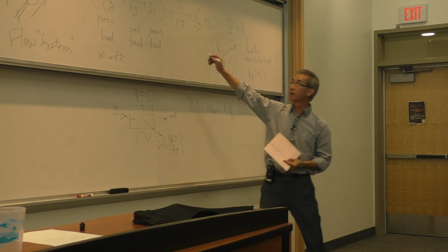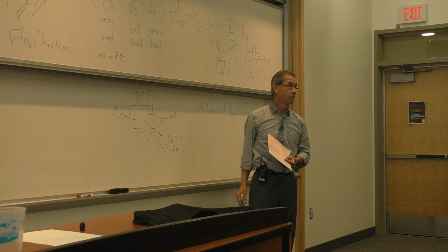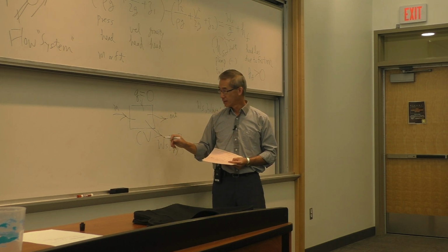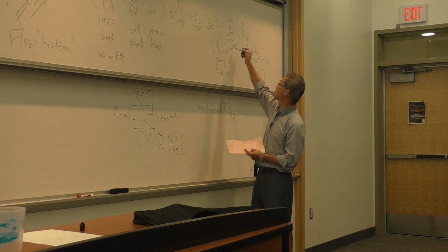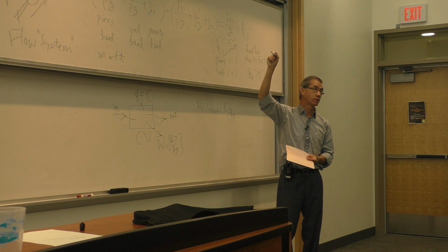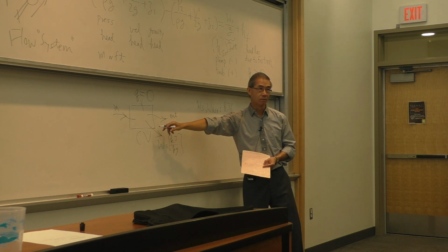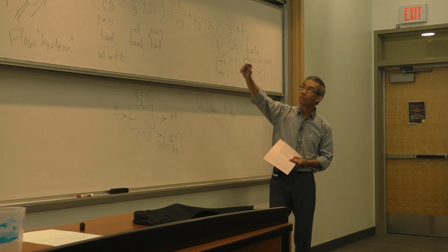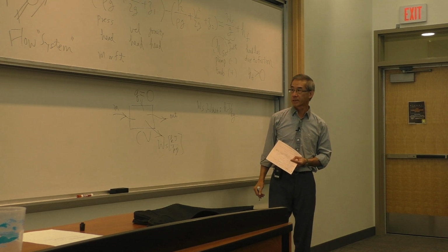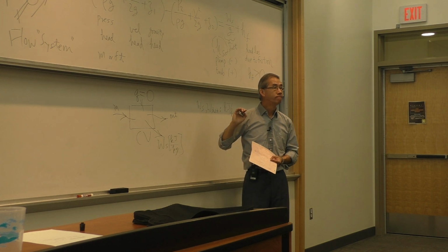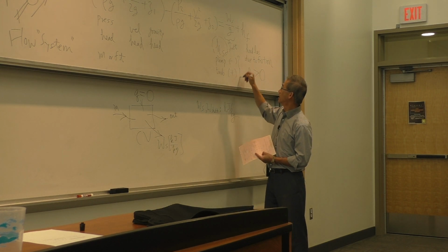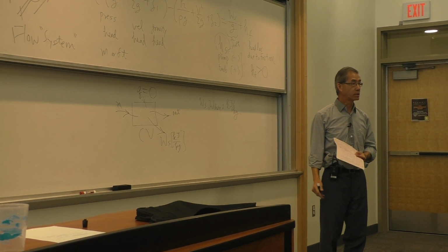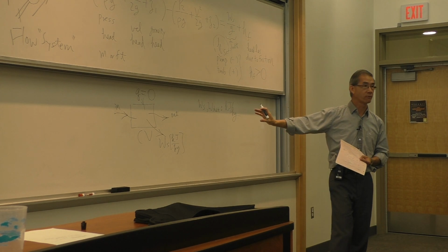So to get to this equation from the energy equation, you will assume adiabatic for heat transfer. And the sign of this W sub S is dictated by our convention, which is plus is work done by my control volume, like a turbine. A pump, which is what we're dealing with in this fire hose, is negative. And that's how all these signs come about, from this convention. So this is just a backdrop of a much more in-depth derivation that will come later.